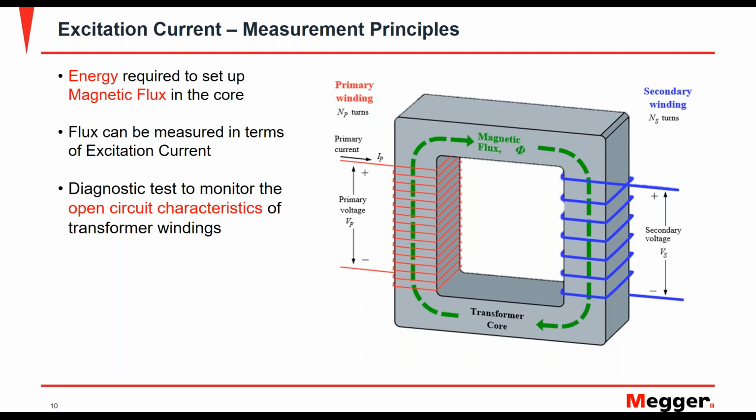There is one common link between these two windings, that is the core and the flux generated in the core. Once you excite the primary winding, you establish what you call a working flux in the transformer core that links with the secondary winding, and that's how transformer action takes place, and you get a secondary voltage induced on the secondary side.